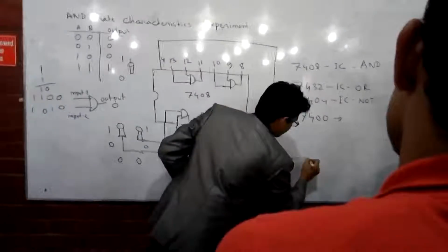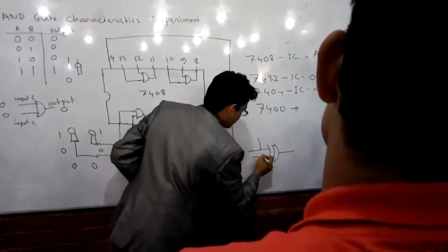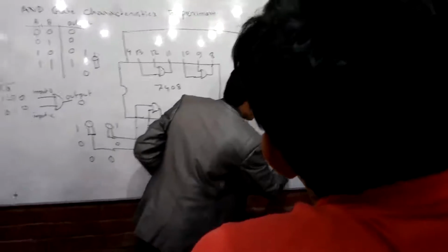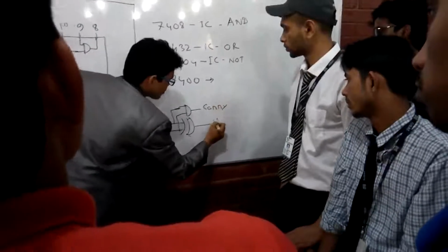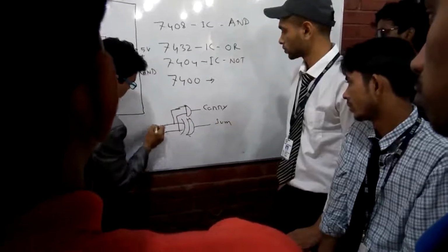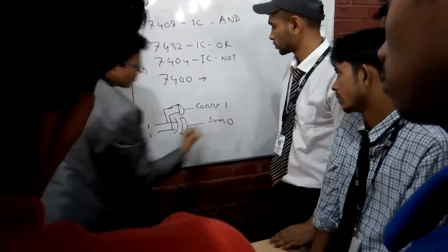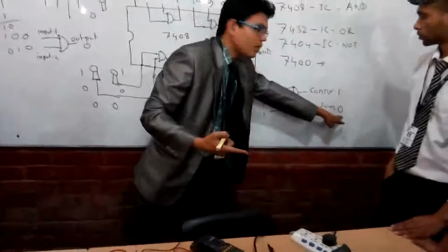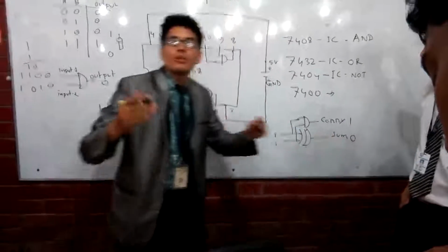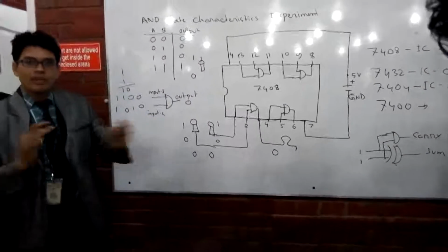Listen, in an adder circuit there is an XOR and an AND gate. These two together make this one stand for carry and this one stand for sum. So if we give 1 and 1 as input, carry will be 1, sum will be 0. So the light for the AND gate will switch on and the other will be switched off. That is how the calculating part of your computer's arithmetic logic unit is made.